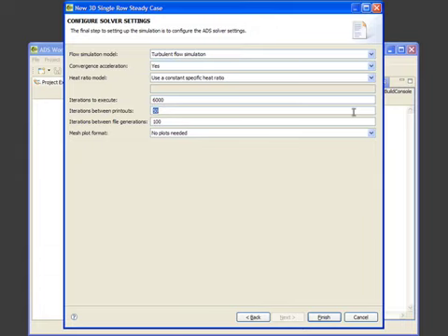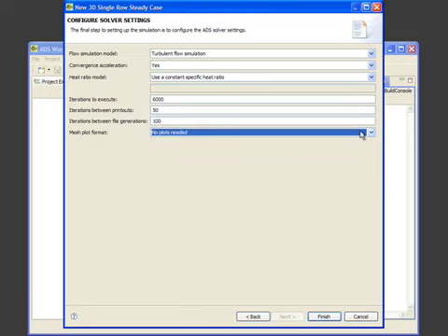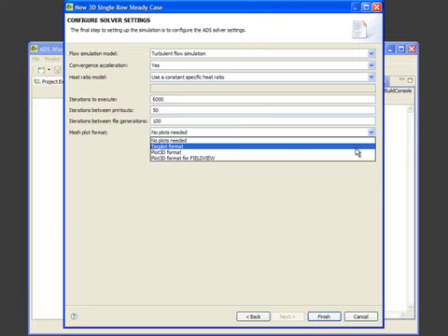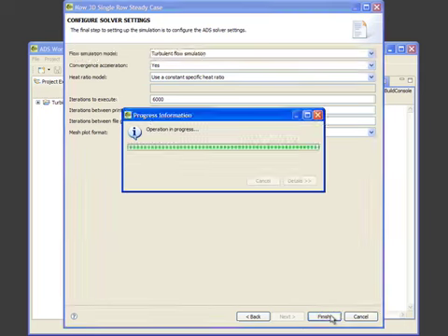Once you have selected the number of iterations to execute, we have two additional variables: the number of iterations between printouts, which are your performance data printouts, and the number of iterations between large file generation, things like plot files and restart files. The reason there are two different ones is that generally plot files and restart files are much larger than the performance data, and they should be produced at a lower interval in order to improve performance of the overall system. Click Finished, and we are done.